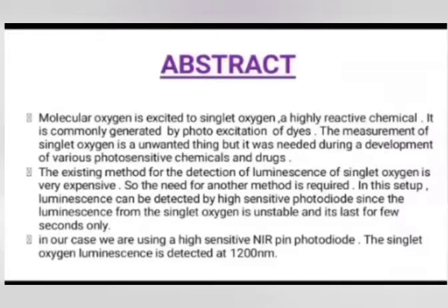In this setup, luminescence can be detected by a highly sensitive photodiode, since the luminescence from the singlet oxygen is unstable and lasts for only a few seconds. In our case, we are using a highly sensitive NIR pin diode. The singlet oxygen luminescence is detected at 1200 nm.